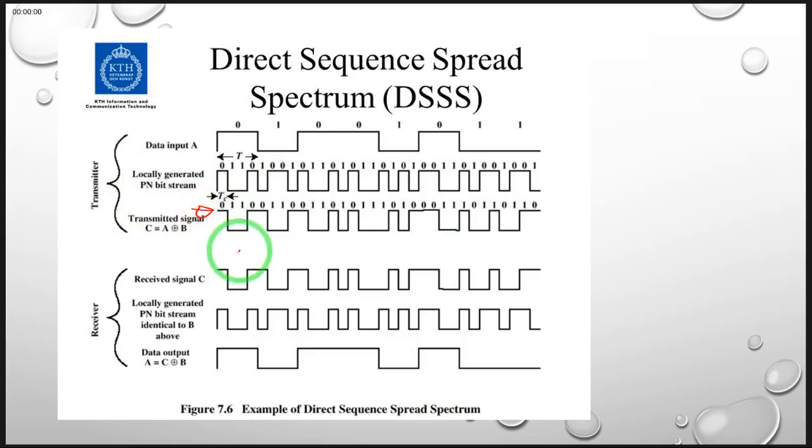And the only thing we can observe with this pulse is that 0 is represented by a positive going pulse and 1 is represented by a negative going pulse. So when we receive this signal on our receiving end, you'll multiply again with a similar sequence like we have already seen, 0, 1, 1, 0, 1, 0, 0. This is what we had received, 1, 1, 0, 0, 1, 1, etc. This one is the same as this one. So we want to be able to detect what we had sent earlier.